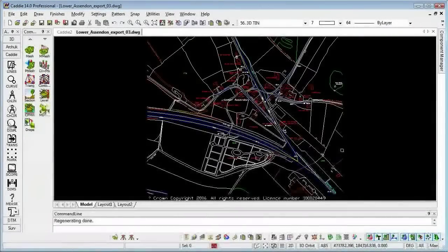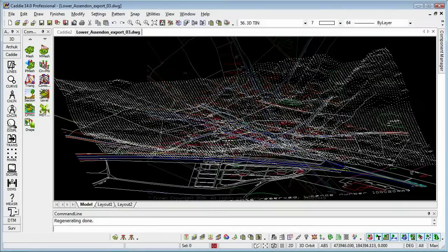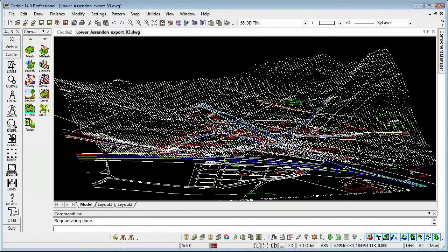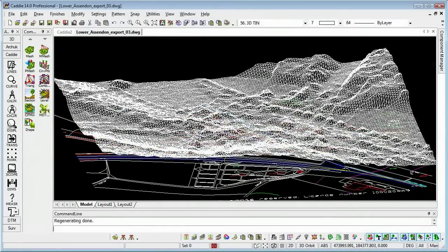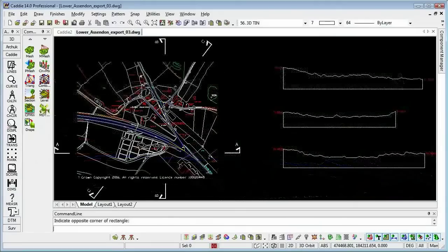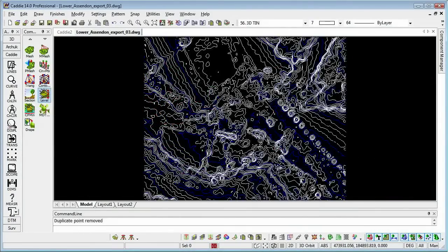Many of you by now will be very familiar with the idea of taking Ordnance Survey mapping data from suppliers such as Promap, incorporating it within your drawings for things like site location plans. What many people are not quite so aware of, though, is how you can take the data that can also be supplied, height data for instance, and aerial imagery, and incorporate that within your drawings too, utilising it to produce site surface models, to produce site sections, to produce site contours, complete with all of the heights noted.